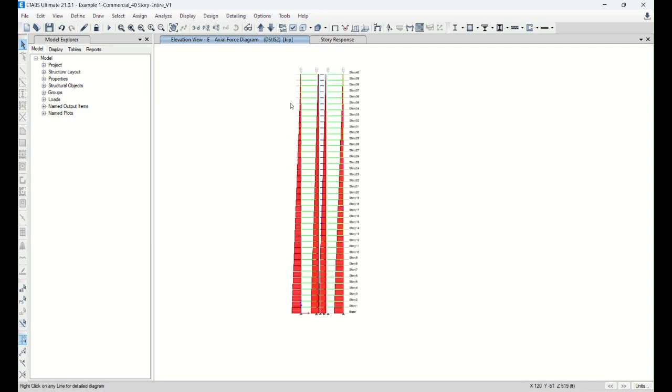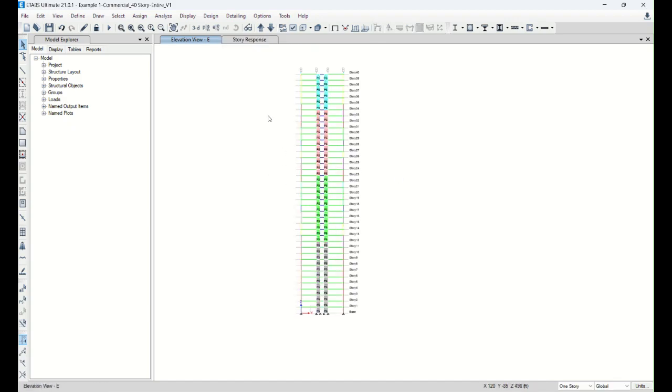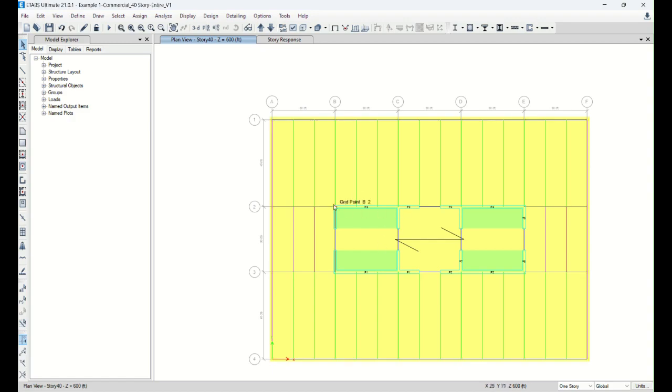But now, since we still lack lateral stiffness in the short direction, the Y direction, we try to add the outrigger truss. Then we'll see how this outrigger truss diagonal member is going to interfere or pick up some gravity forces and dump them to the wall. That's something we need to be aware of, and I'm going to show you. So next step, first, take a look at your plan.